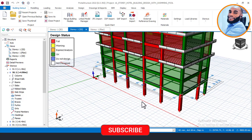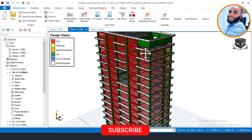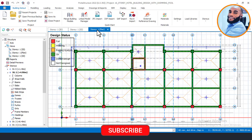Even if some of your members are showing green, which is okay, I still advise that you check each of the members to see the kind of reinforcement that the software used to design for that member. With that, I will make story 1 active. I'll come to the story 1 plan view here, click on it, and make sure that story 1 is active.